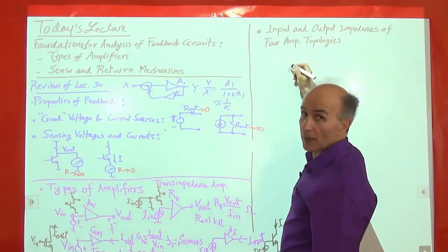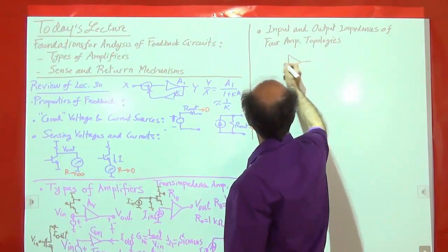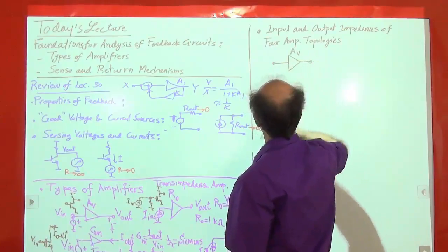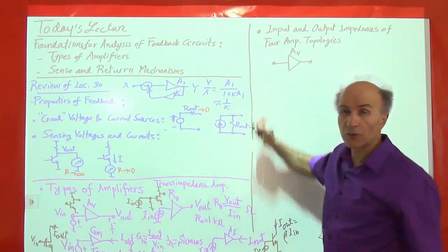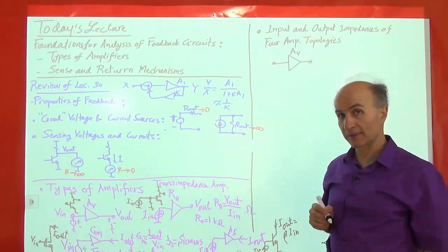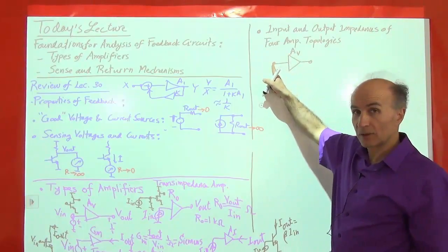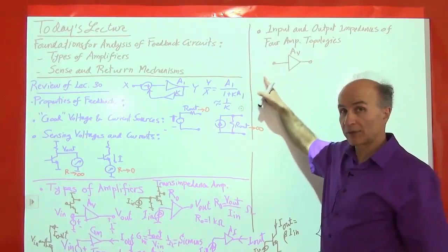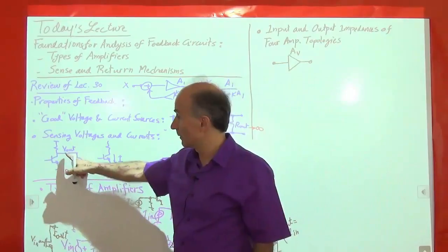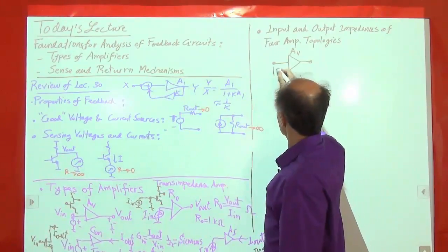Okay, that picture helps us understand what we should do. All right, so here's a voltage amplifier. I'll just say AV so that we know it's a voltage amplifier. What should the input impedance of a voltage amplifier be in the ideal case? Well, the purpose of this circuit is to sense a voltage. And when we sense a voltage, we don't want to disturb the preceding circuit, just the way this voltmeter must not disturb the preceding circuit. So ideally, the input impedance of the circuit is infinite.